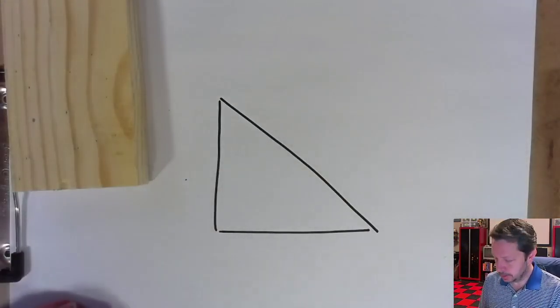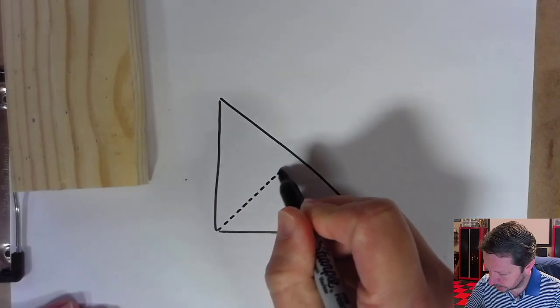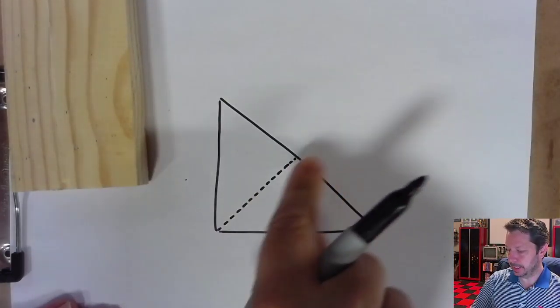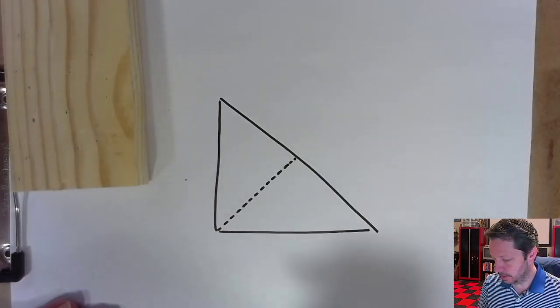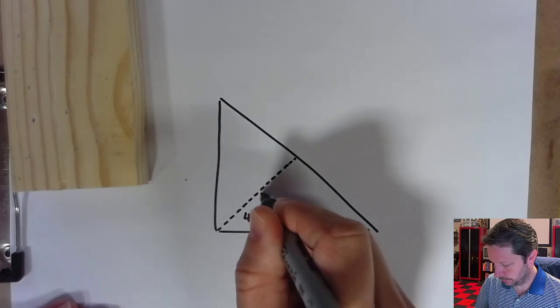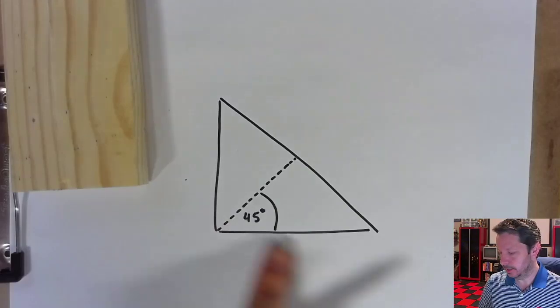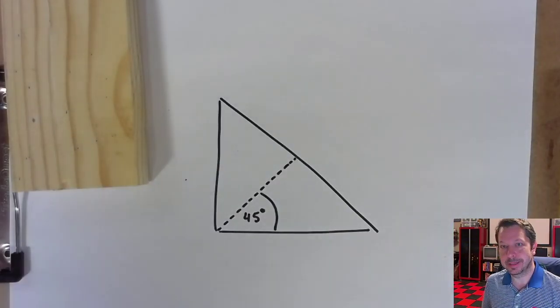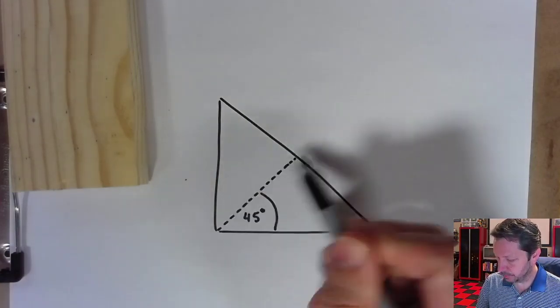And this is the weld. And the throat of the weld is this plane here that goes into the page. So it's tilted at a 45-degree angle here. We're also assuming these angles are 45 degrees, so this leg and this leg are the same length on our welds. So that's the throat.